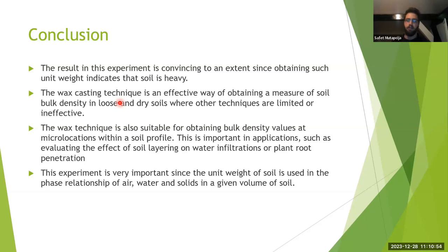Depending on the tectonics, some parts are more dangerous than others. So you have the expected magnitude of the earthquake, you use that acceleration, and you design the foundation based on it. It's more structural engineering than foundation engineering, but it's really important.